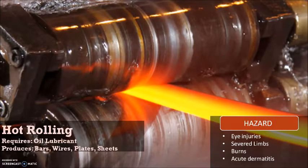The hot rolling process. After the molten steel has been formed into blooms, billets, slabs, and tubes, it will then proceed to the hot rolling process. The hot rolling process is a metal forming process wherein the hot steel's thickness is reduced by rolling it into a pair of hot rolls. The hot rolling process will produce steel in the form of bars, wires, plates, and sheets.